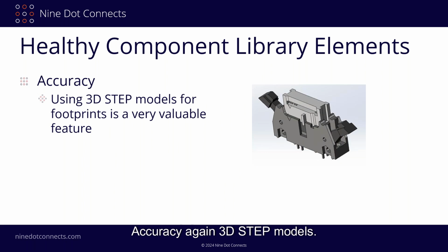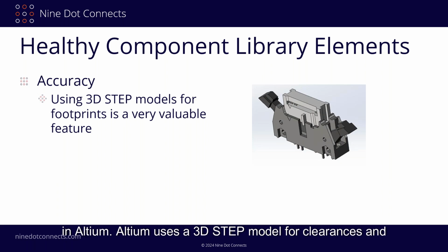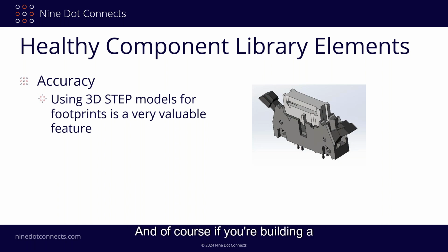Accuracy, again, 3D STEP models. In our libraries, and with our customers, we always suggest that you use 3D STEP models. If you're not using them in your libraries, you really should. It's so good, especially in Altium. Altium uses a 3D STEP model for clearances and things like that. And of course, if you're building a footprint and you have a 3D STEP model from another source and they fit together, it's always a very good feeling. And if they don't fit together, something went wrong. Either the footprint went wrong or the 3D model is wrong, but something needs to be checked out. But when they do fit, it's really nice.